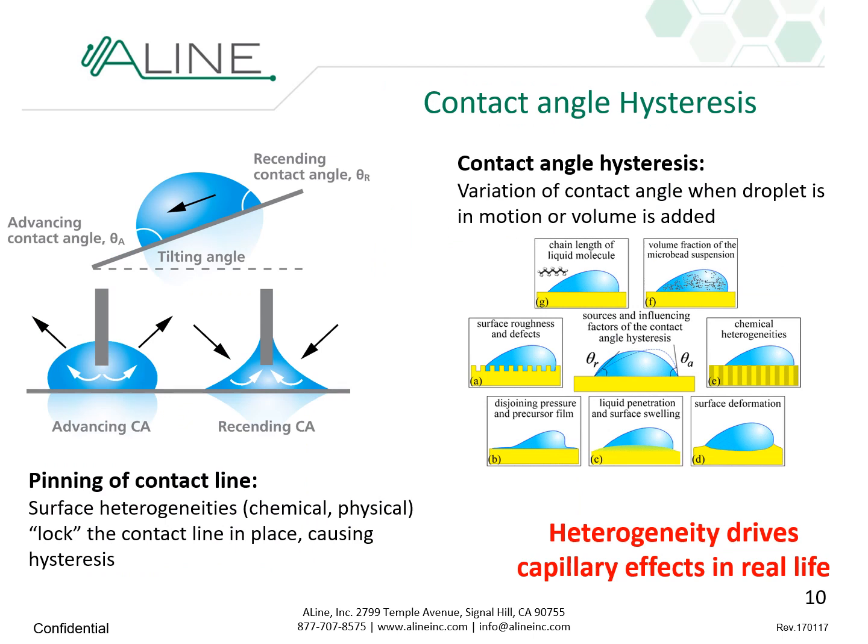One thing to keep in mind is that all of this classification is driven by a static effect, when the droplet is at equilibrium and measured in a static condition. Once we start looking at dynamic effects, which is what we like to do in microfluidics, where we want to move fluids around and not just have them stay stuck, there are other effects that take place, called contact angle hysteresis. If you take a droplet and tilt it, the droplet will move, but the contact angle will be different between the front and the back. Likewise, if you add or remove liquid from a droplet, you might end up with contact angles that change depending on the volume.